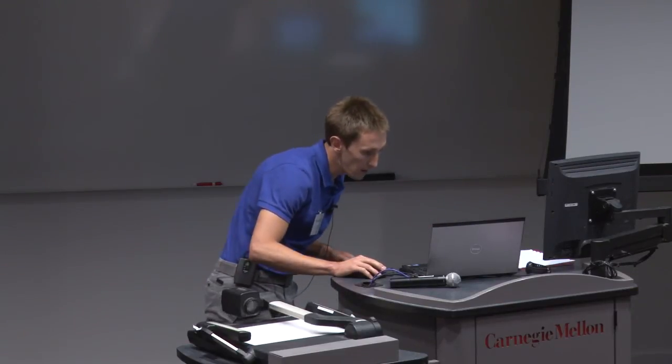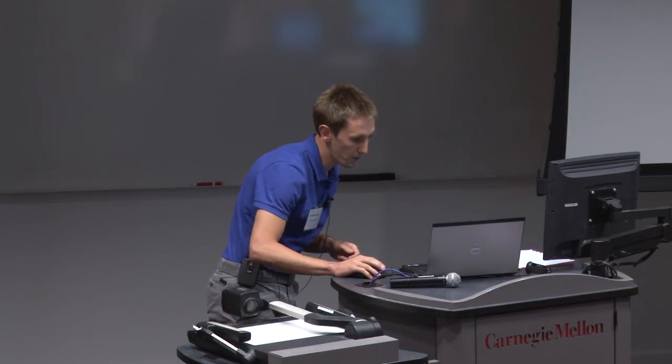Just curious, you played with optimizing the timing of adding additional power, but what about the magnitude of power that you add? Yeah, as you probably know, with these metabolic experiments, you don't get your data instantaneously like in a simulation. So there were a lot of things which we just chose by trial and error. I think certainly in prostheses, Josh will have a lot to tell about the amount of force. So what we did was just simply set a fixed air pressure of 3.5 bars, and when the actuation was meant to start, we just completely opened the valves. Force increases somewhat gradually because the pneumatic muscles don't fill instantaneously, but we didn't control force at all.